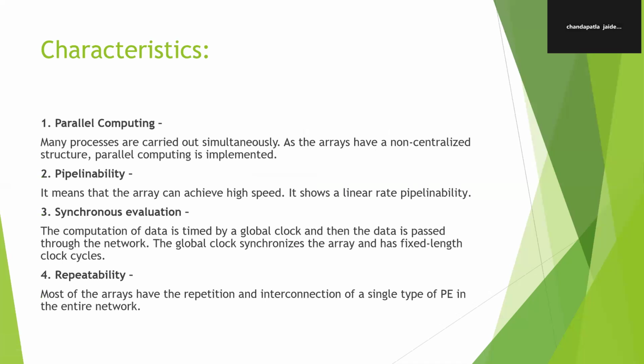Characteristics. Parallel computing: many processes are carried out simultaneously as the array has a non-centralized structure. Parallel computing is implemented with pipelinability, which means that the array can achieve high speed. It shows a linear rate of pipelinability. Synchronous evaluation: the computation of data is timed by a global clock, and then the data is passed through the network. The global clock synchronizes the array and has fixed length clock cycles. Repeatability: most of the arrays have repetition and interconnection of a single type of PE in the entire network.